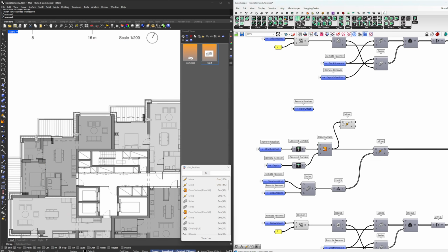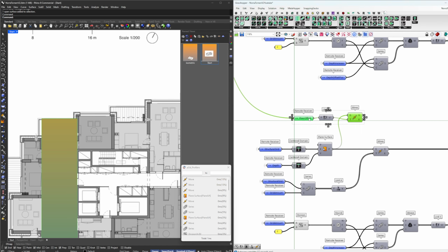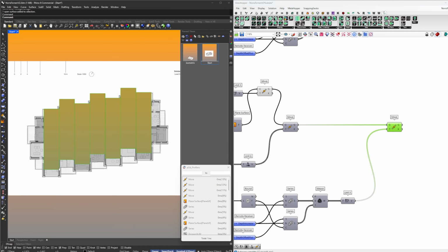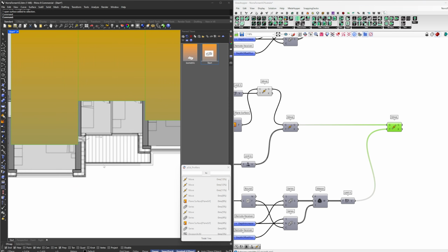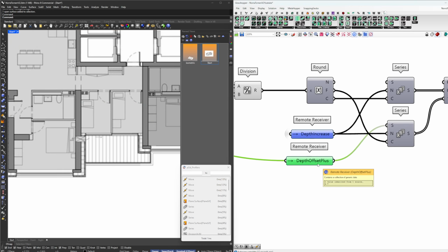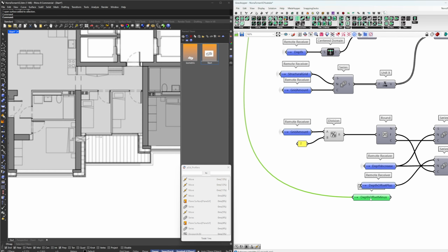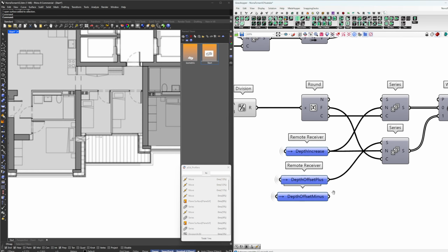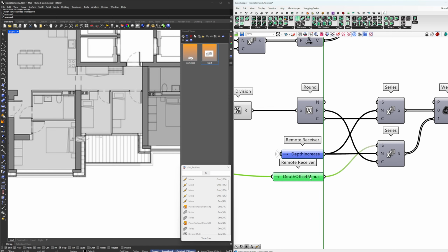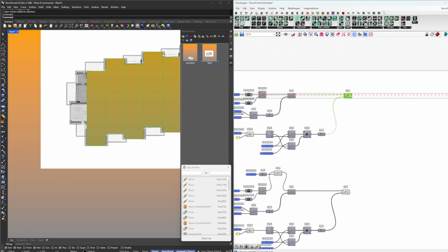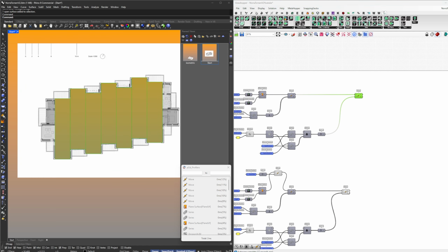So we're gonna move this individual to a y of this. Okay, nice. So then this one goes there. And the thing is, this guy needs to go to here. So we don't put the depth of 2.7. No, we're now gonna work with the depth minus. So instead of going 2.7 forwards in an x-axis, sorry, in a y-axis, it goes minus 0.1, 0.2 back. Actually, now we have our two floor plates. So this is floor A and this is floor B. Perfect. Okay.